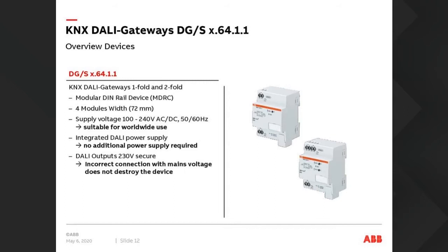As I said, we have an integrated DALI power supply, and the DALI output is 230 volts secure. What that means is that a lot of people would come to us with devices that had been broken. Somebody had mistakenly connected 230 volts onto the DALI side. So again, the boffins in the factory did a bit of work on this, and they now have 230 volt protection on the DALI side. So even if you connect 230 volts to it, it will be fine. It won't do anything to the device. The device will still work fine once you connect it properly.